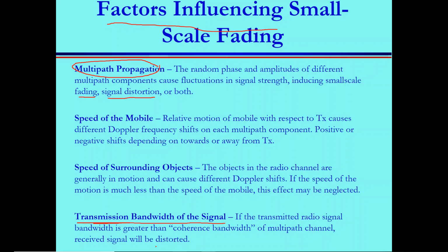While in copper, since the coherence bandwidth of your medium is short, you cannot send your signals with high speed, because high speed means you shrink the duration of your symbol. When you shrink the duration of your symbol, the bandwidth becomes large, becomes more than the coherence bandwidth of your channel. Your system gets messed up.